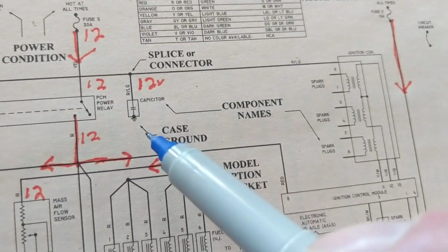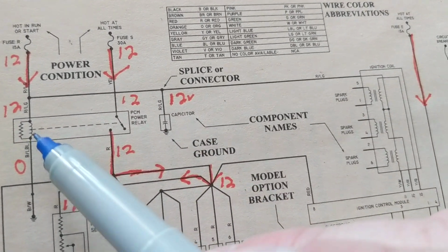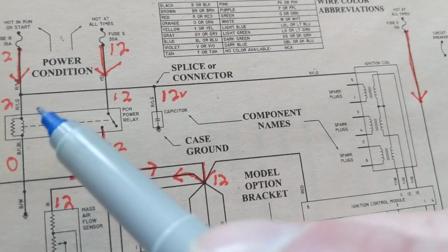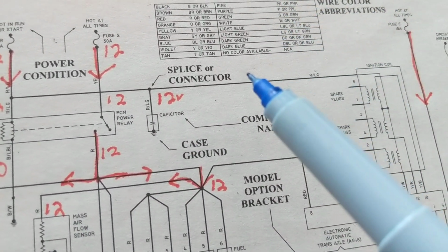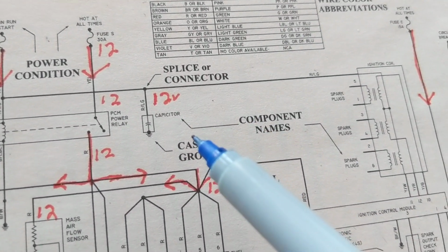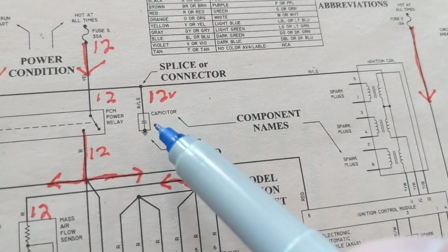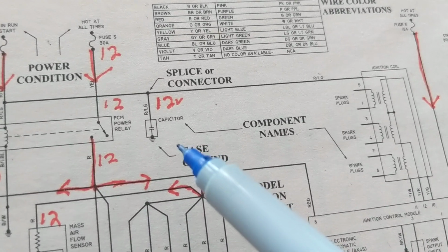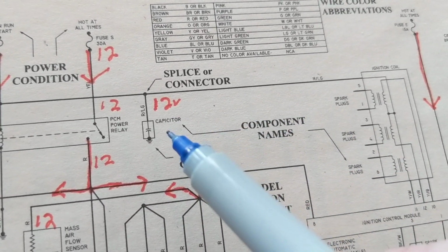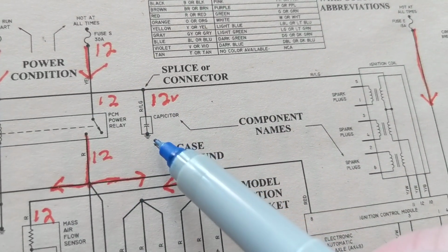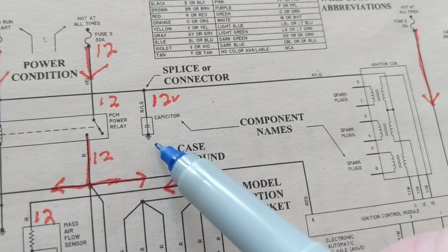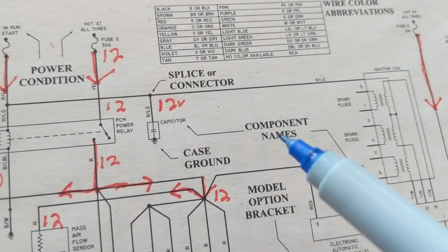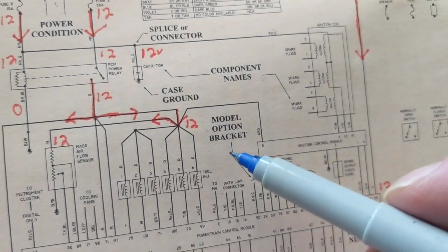It might take 15 minutes, it might take 20 minutes, depending on the resistance of this relay. So you turn off the key, and the radio is still on. You say, why is the radio still on? Why are some accessories still on? Well, the capacitor is still discharging. If you want to discharge it quickly, what do you do? You open the door. When you open the door, boom, a discharge right to ground through a switch, and the capacitor loses its charge, and the accessories go off. If you ever wondered why that happens.